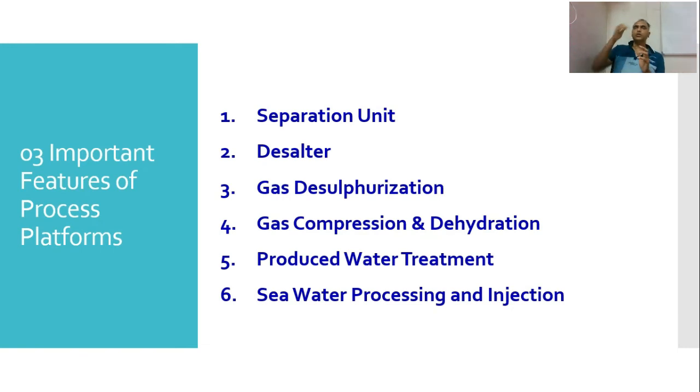Okay, fine. So now the gas which we have taken out, separated. This gas we cannot directly sell because this gas has water vapor. This gas may have sulfur content, because of which it is called a sour gas. Sour gas means it has sulfur content in the form of hydrogen sulfide, that is H2S.